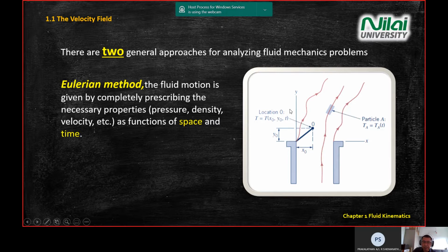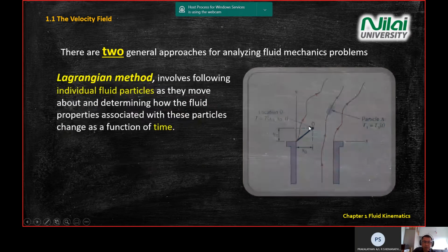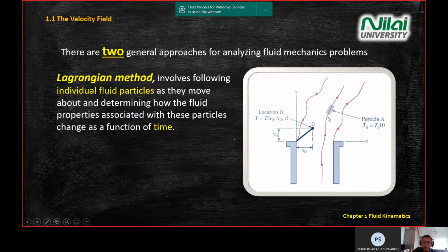Now, the second method is simpler, where it focuses on the individual smoke particles, and it follows the particles, rather than there being a fixed sensor as in the first method. So the Lagrangian method is focused on the individual particle and on time only. It means you follow the individual particles, while Eulerian just stays there and measures whatever comes its way. So these are the two big differences. Of course, you can read the more detailed explanation from the slide.